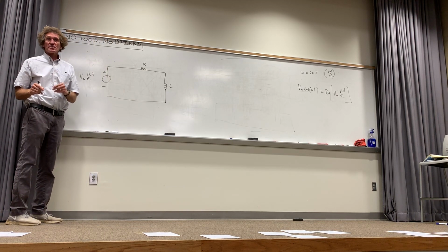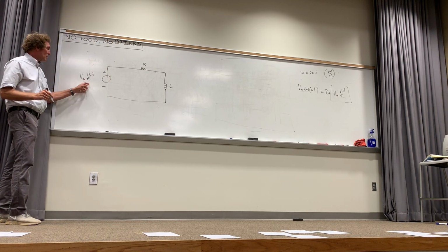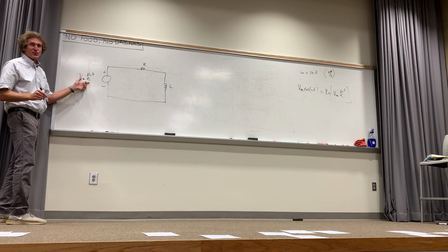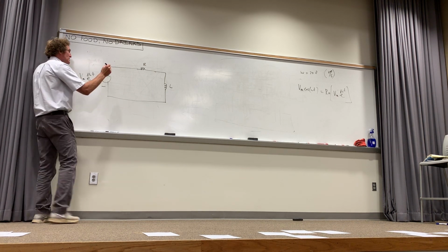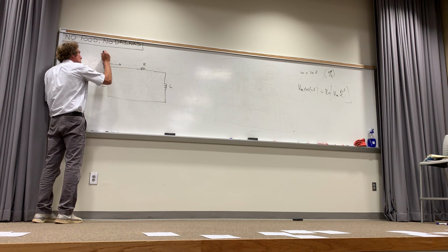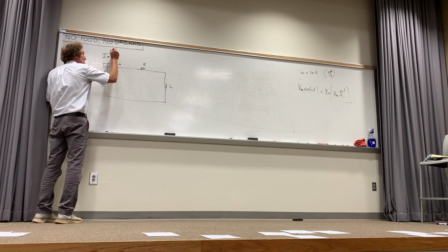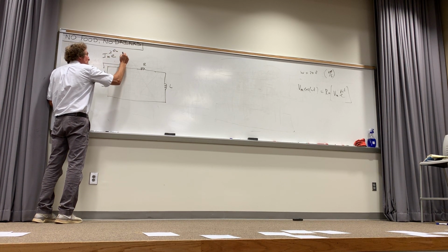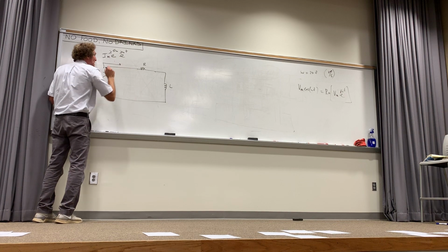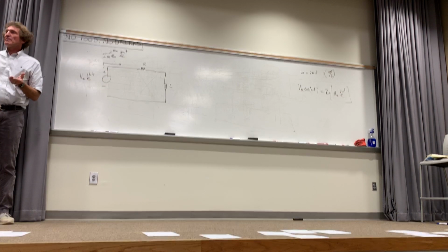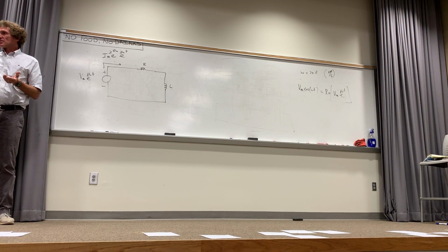And now, listen to me. This is something that's called a steady state response right here. It will give rise to a current, and I can't prove this right here, but I can write the equations and prove it one time with the differential equation, but I'll just tell you this. It's going to give rise to a current that's going to have a magnitude Im. It'll have a phase angle e to the j theta m, and it will be oscillating at the same frequency. It will be e to the j omega t, whatever omega is. Do you follow? So it's going to have the same periodicity, or rate of change. All right?